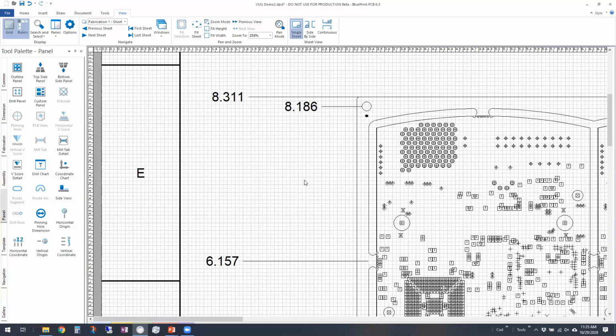It's basically just the location where the web route ends, and then they put drills in there. So you have to know how to do some NC programming in order to do that on the fab side. And what's happened is we've made you the designer an NC programmer, because that's the only tool you had to do it. And if you did it in CAM 350, trying to get a document from the result was very difficult. A lot of people end up in AutoCAD trying to do that.